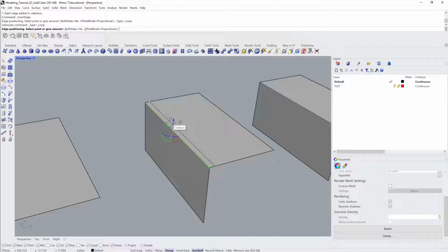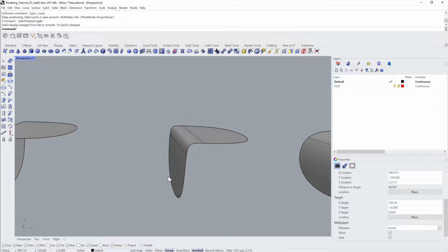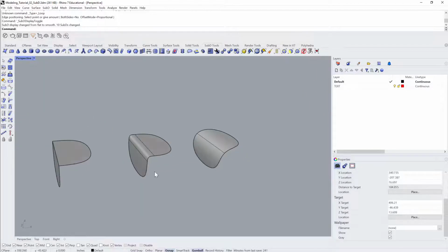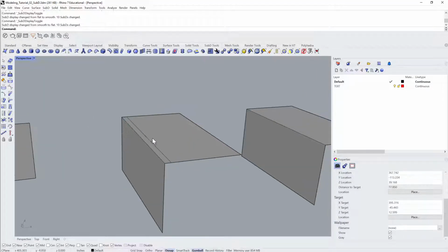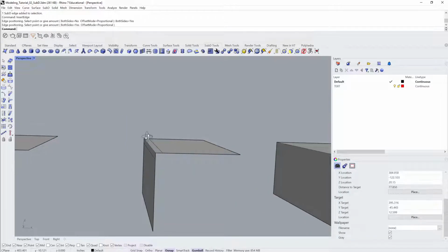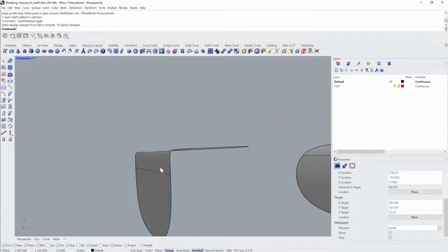And you can see here that there's some options. By default, it's going to be on one side only. But even already, you're going to see that that's controlling, compared to this one, how much the curvature is happening, right? So let me undo that, because I can also, the command now is InsertEdge. I can put it to both sides and get this very even offset on both sides. And now when I hit tab, I get a really nice transition here.